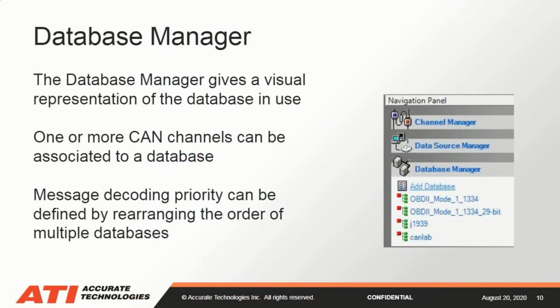The next manager pane we see is called our Database Manager. And the Database Manager gives us a visual representation of what databases are available to the CANLab software workspace. So you can reorganize, reorder, and add databases as you see fit. This can be done in real time. So even if you are in the middle of running a simulation or collecting data, if you need to add a database, you just go ahead and click on the Add Database button and search, grab your database and add it, and then it becomes available to decode any of those messages that you see coming through at any time.